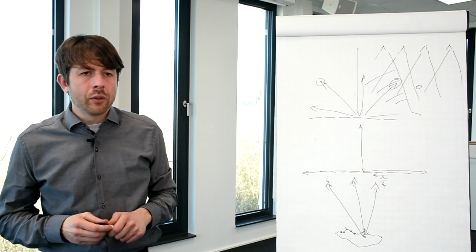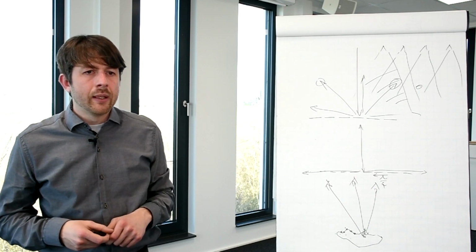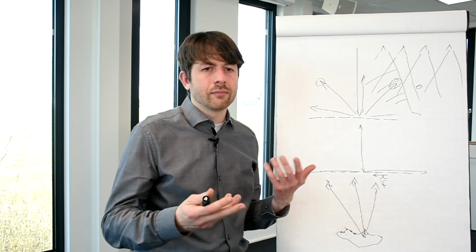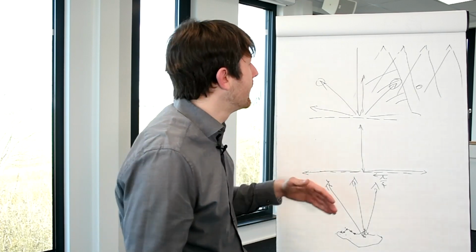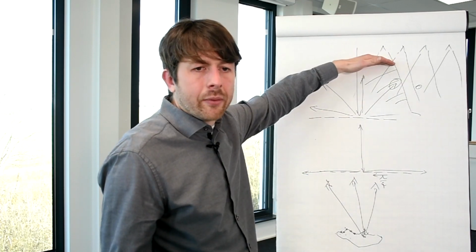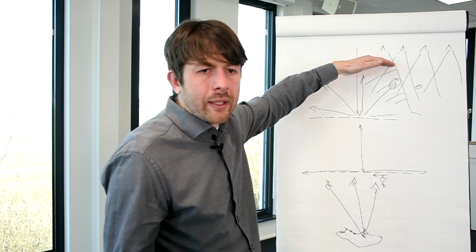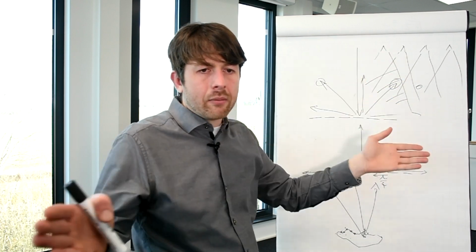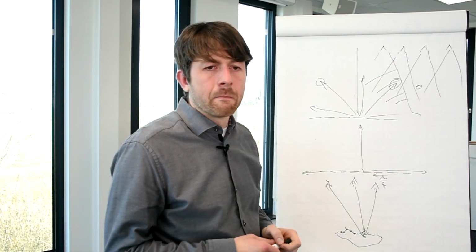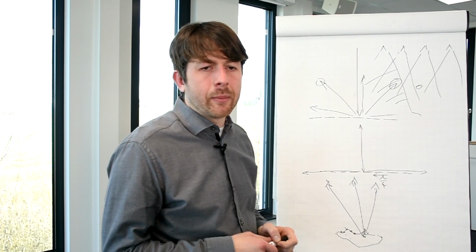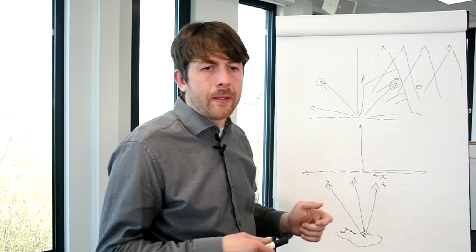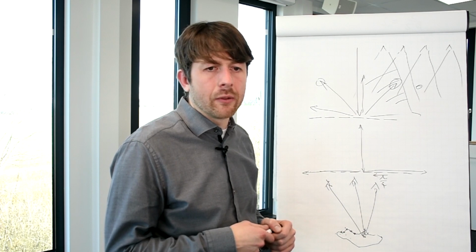What is the resolution you want to see? Usually, as an engineering approach, I would say I'm living with lambda by 2 and I adapt my antenna opening angle, so I limit my aperture size. But that really depends how much you want to invest and what image degradation you want to accept at the end.